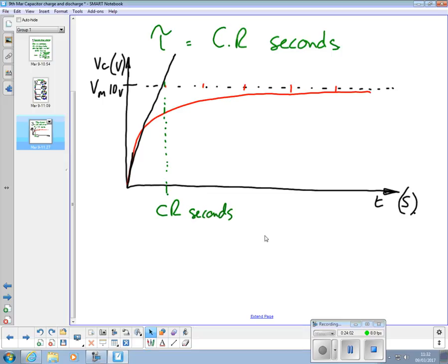The time constant is the time it would take the capacitor to reach the initial applied voltage if you keep a constant current. If you keep pumping 1 amp in, your voltage will keep rising. The problem is your capacitor has a working voltage, and once you go above that by a significant amount, boom.